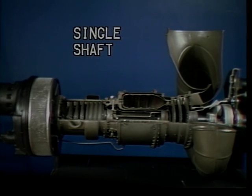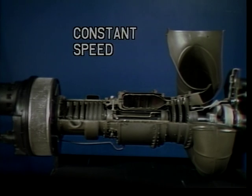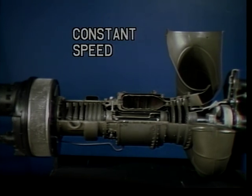The term single shaft means that there is one continuous rotating shaft supported by sleeve bearings at 3 critical points. The term constant speed indicates the RPM of the shaft will be set at the desired speed to meet predetermined application requirements. This speed is kept constant by a fuel governing system.